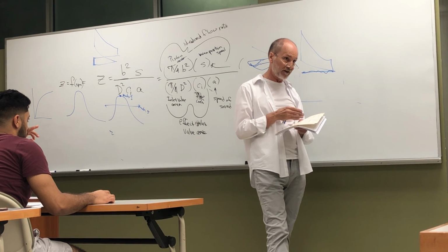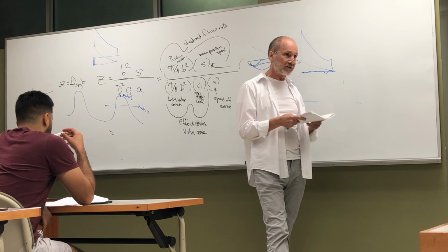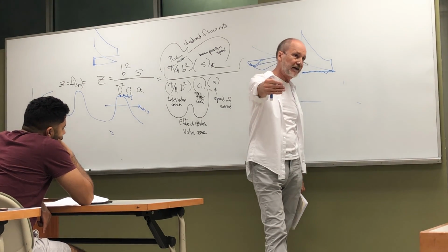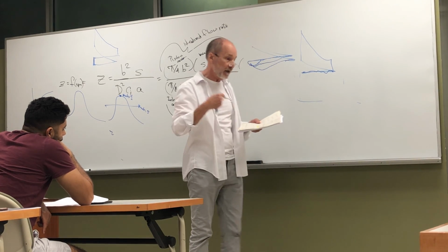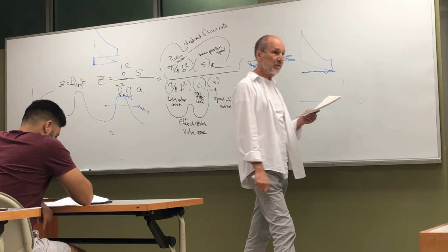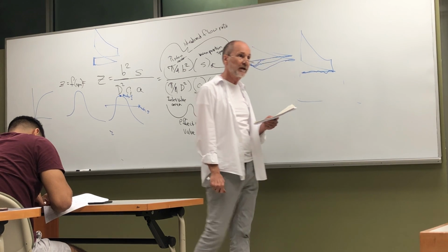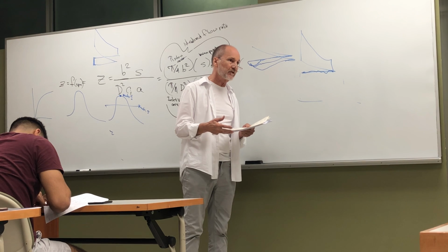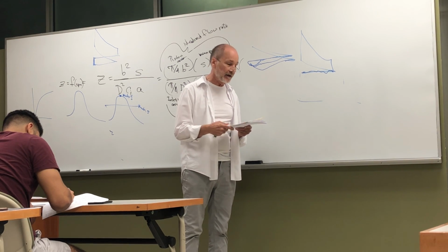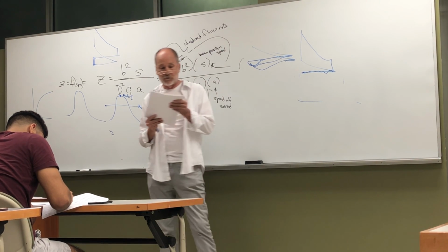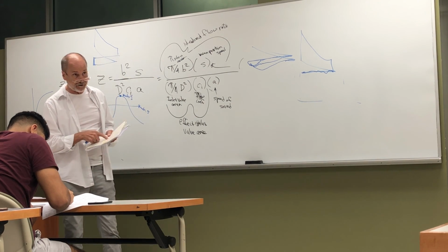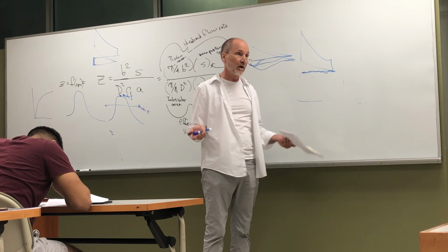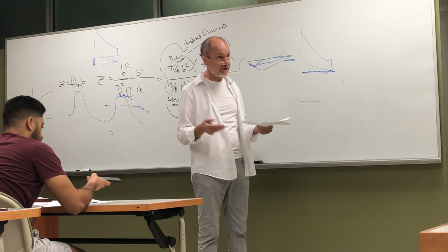If you're talking about the far left at the bottom, that's a situation where you've got your foot off the gas because you don't want to run into the guy ahead of you. And the one in the middle is back at wide open throttle. That's when we'd like pressure, but we don't want pressure from residuals. We want pressure from fuel and air because we want to make more power. And you can do what they did here just to the right, and add a supercharger and turbocharger. You can put bigger valves in. You can put a higher lift cam, more duration in the cam.